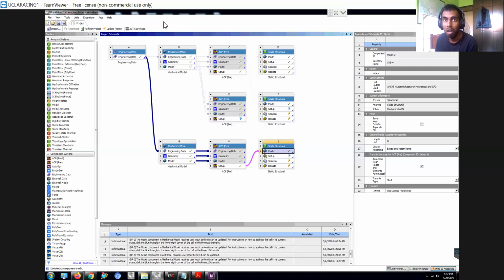Number two is factor of safety. Generally, I go with a factor of safety of 2.5. How I arrive at that number, for formula stuff: typical metal structures have a factor of safety of 1.5.